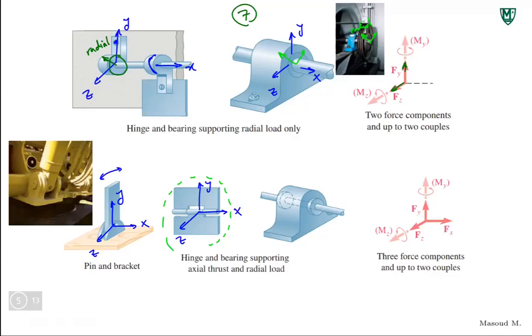And also the bearings, which are a little different from the bearing we saw at the top when I was giving you an example of a bearing for a fan. It could be one of those two, depending on how you fix it. But typically, these are the bearings at the end of a shaft. So not only do they do what the previous one was doing, but they also prevent motion along X. Let's see.